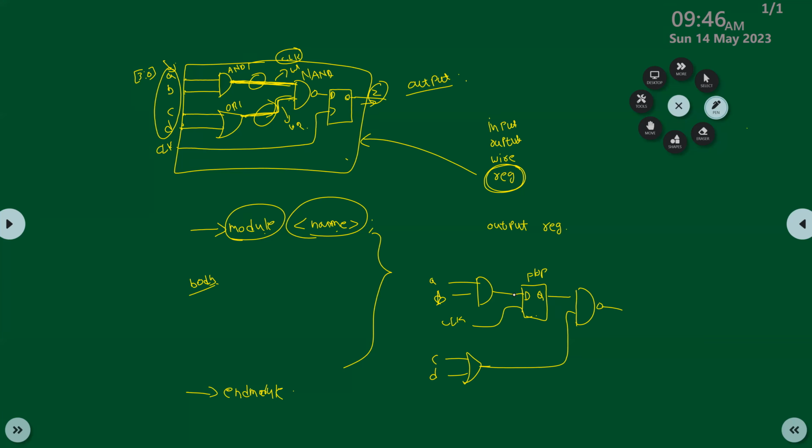Then you have to declare these: this is, let's say, wire 1, this is clock 2, this is wire 2, this is wire 3 only, but you have to declare this wire 3 as a register. So reg W3 you have to define. Understood? Z as it is, output Z, but the remaining wires we declare W1 comma W2. So remember, whatever the wires which are originating from the register output, those you need to declare as a register, right?